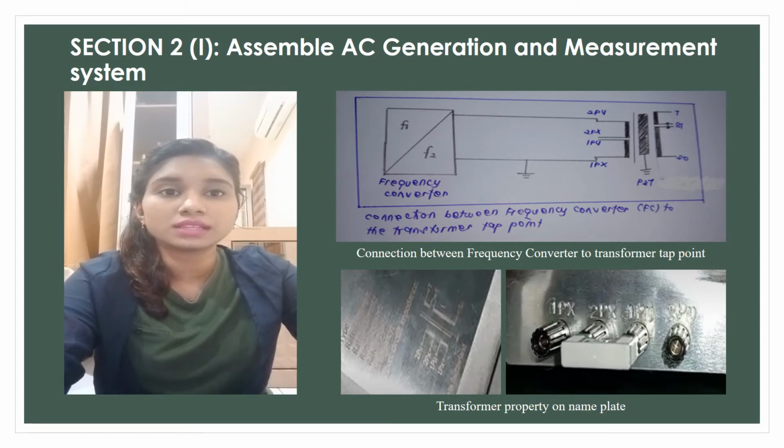To obtain the high voltage level, the 2 PX and the 1 PU should be connected together at the primary side so that the whole potential can be obtained from the 2 PU and 1 PX. The potential that we can obtain is from 0 kV to 100 kV. The voltage from 2 PU to 2 PX is only 220 volts, which is not enough to achieve the required voltage. That is why the connection of 2 PX and 1 PU is very necessary.